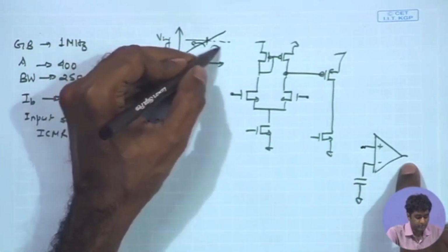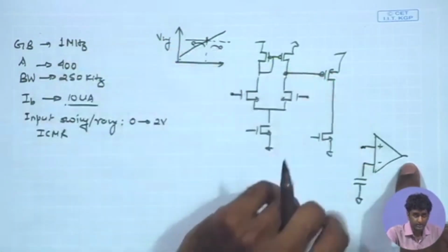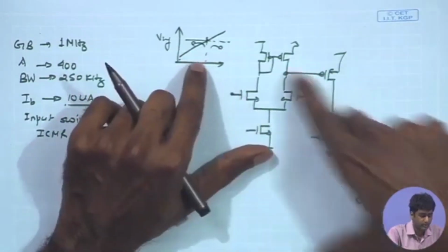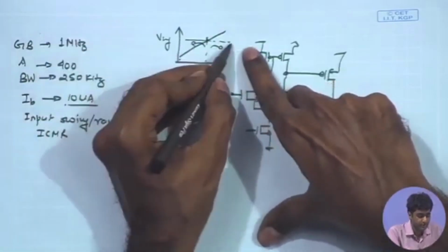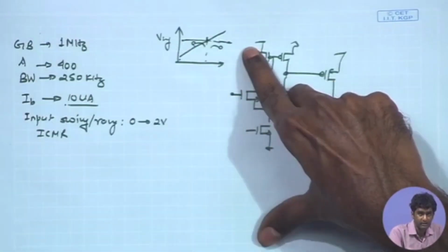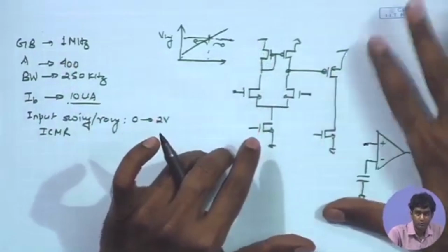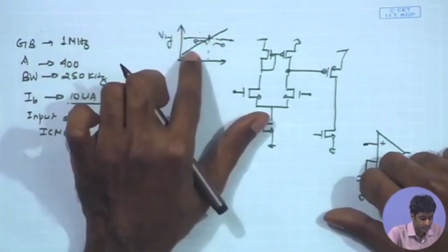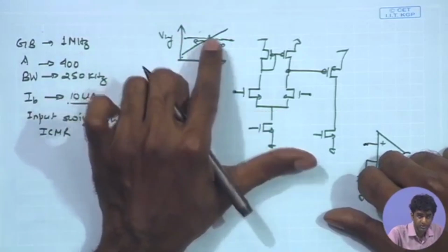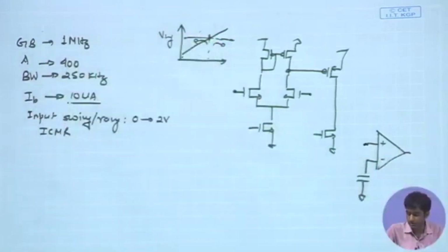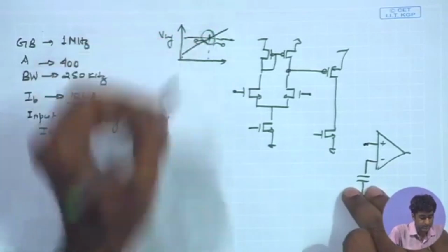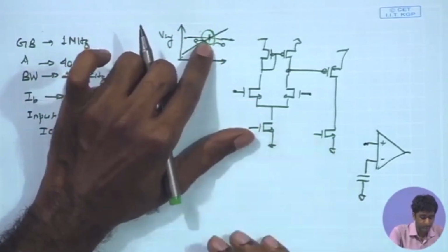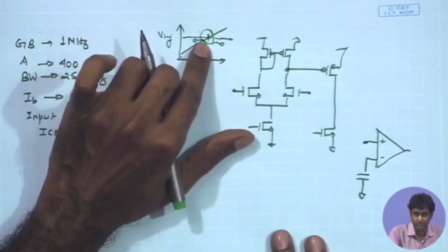If you are far away from these 2 points and the comparator gain is large enough, definitely the comparator output will be deterministic. If the V ref is sufficiently different from this sampled value of V in, definitely the output will be close to VDD or ground. But the moment V ref approaches the sampled voltage, that is the crucial instance at which we should be getting timely resolution, timely switching of the comparator.